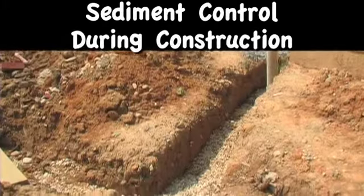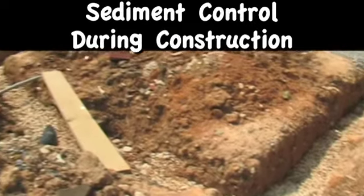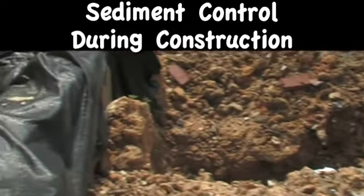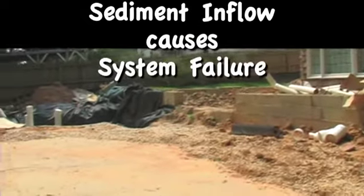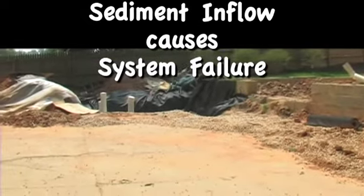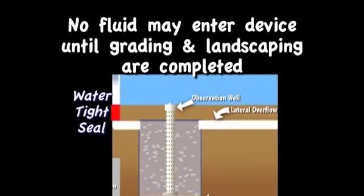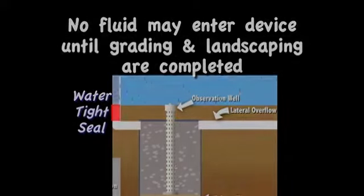The prevention of sediment intrusion and stormwater runoff into the infiltration device is perhaps the most important factor to consider during construction. A sediment flow into the system during construction may cause the device to fail. The infiltration practice should be maintained as inoperable until all grading and landscaping has been completed and the final erosion and sediment control measures have been installed.